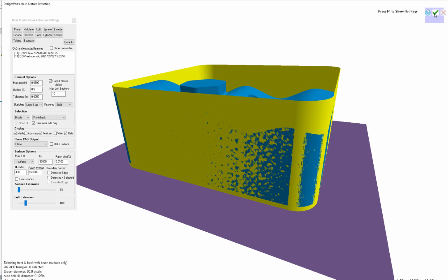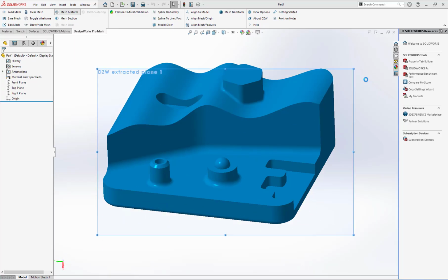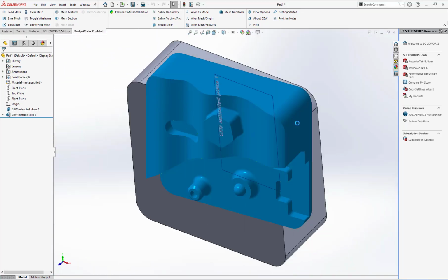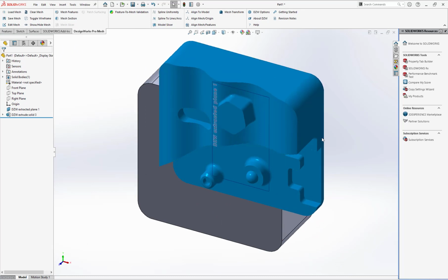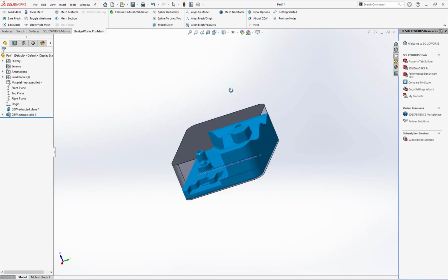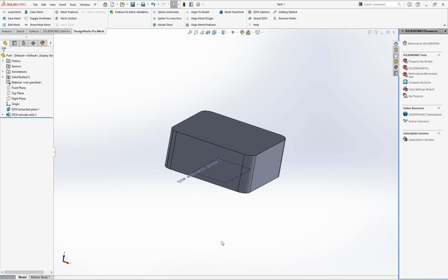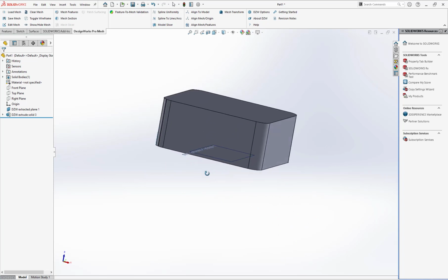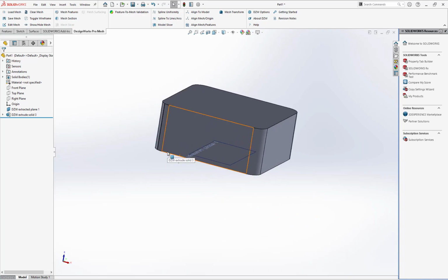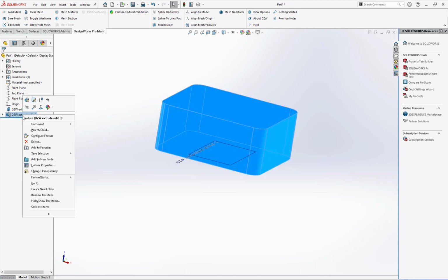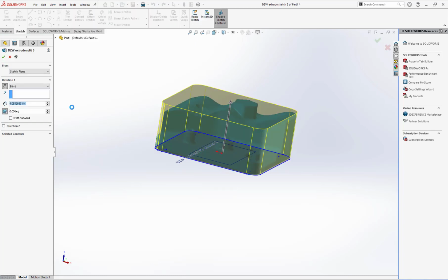With other products, you accept this, then you, the SOLIDWORKS or Inventor guy, would have to go back and modify it in a tree. Well, we don't want to do that. So we did that in that new window for you. So you can see it started at the bottom, did the extrude, and if you interrogate the solid, say edit feature, you'll see the draft is 0.